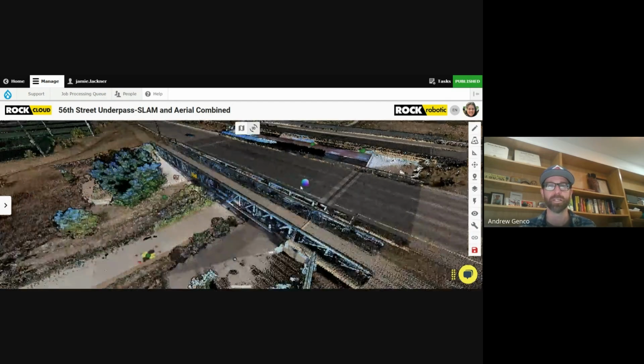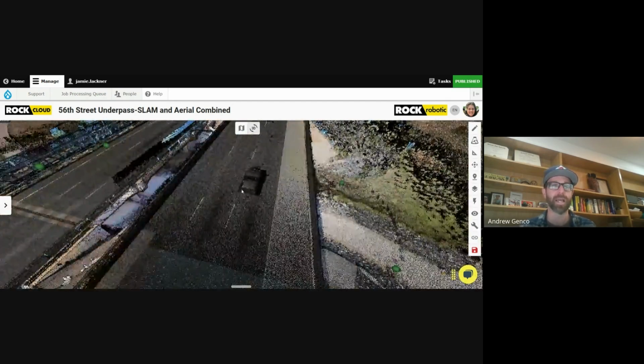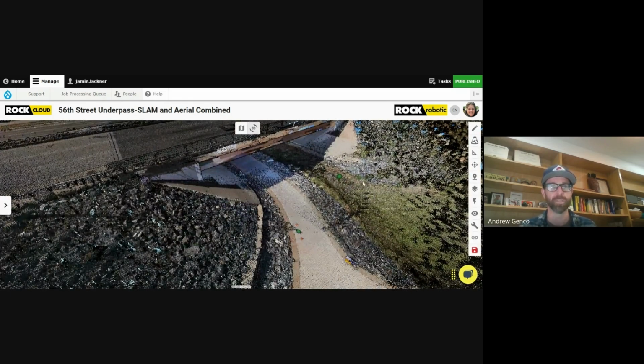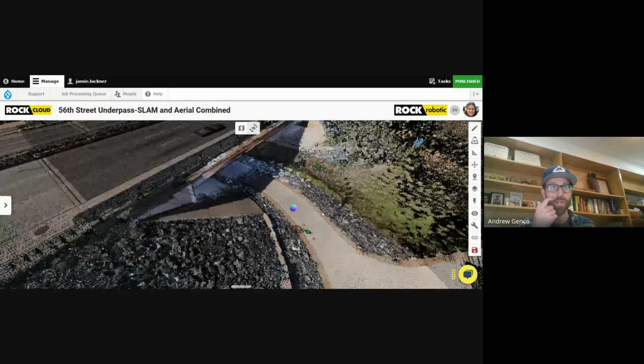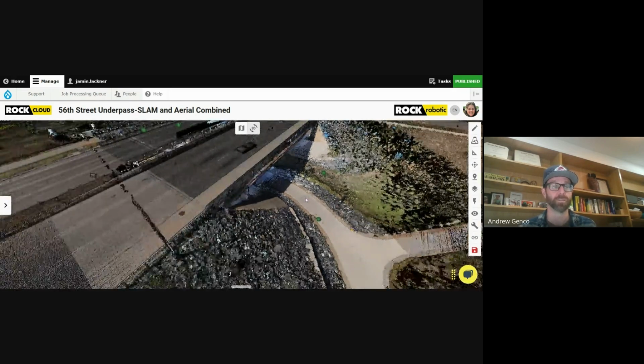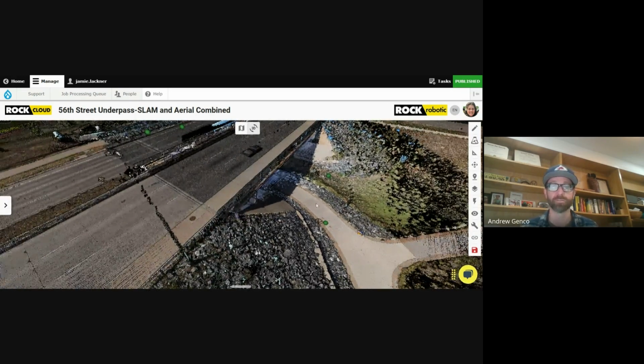We always like to think it's a bit of accuracy in, accuracy out. So your final accuracy, if you're aligning to GCPs, is only going to be as good as the confidence and the accuracy of the GCPs that you survey in. So if they have a higher RMS error, then it's likely that you might see decreased accuracy in the final results.